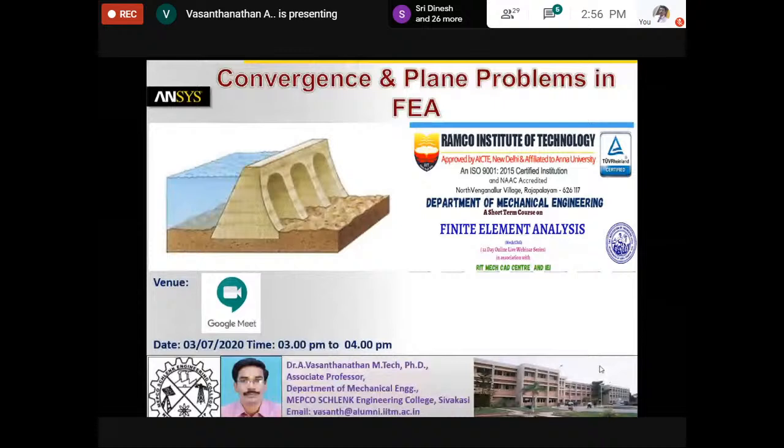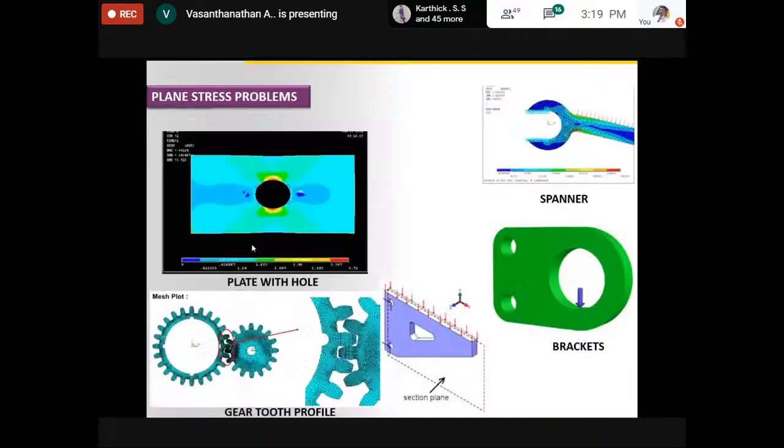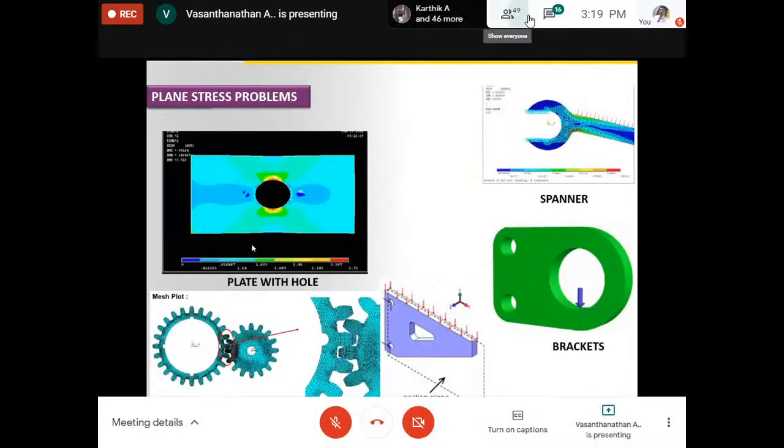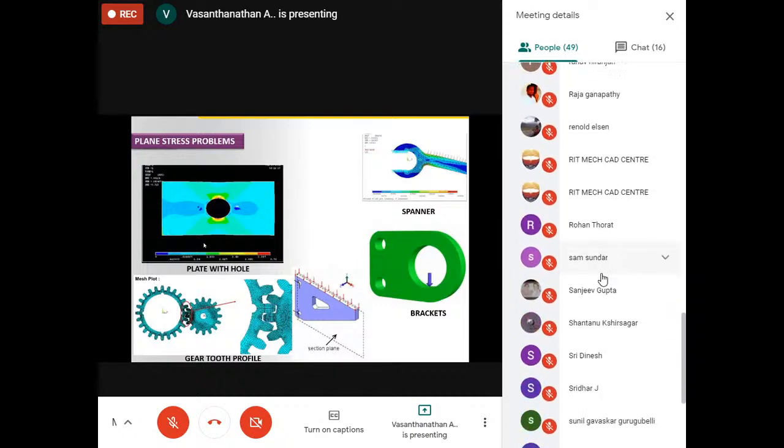This paper does not have any strength; it's a very weak object, you can imagine. No, it's very strong in the in-plane direction. You can check. Try to tear this paper. If you tear this paper along the thickness direction, it's a very easy job for you. Now if you want to tear this paper along the in-plane direction, it's the toughest job for you. Correct? So the in-plane strength is very high. Such objects, having small thickness, come under this category.